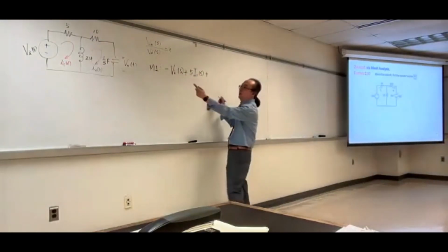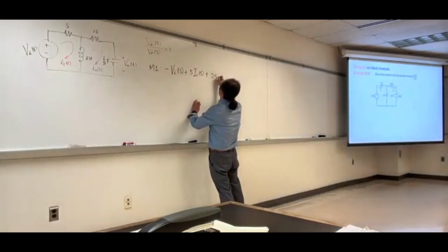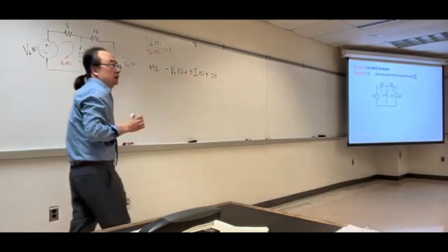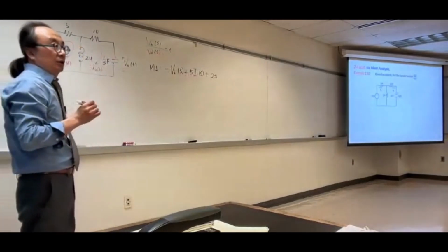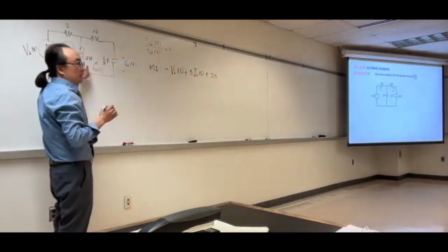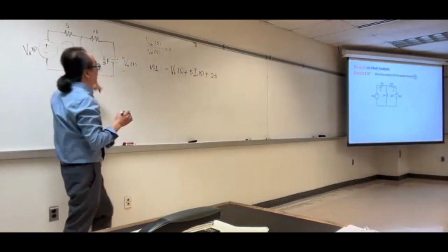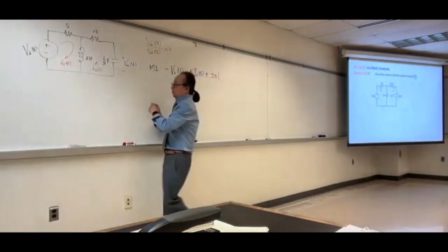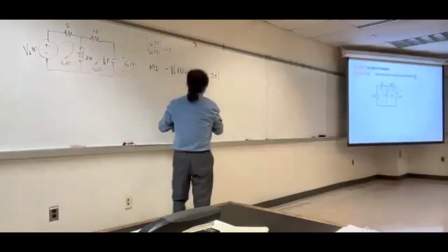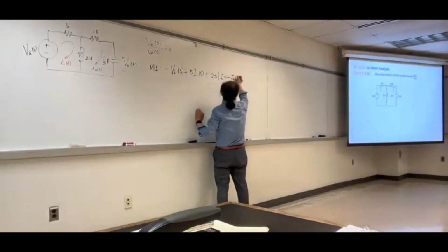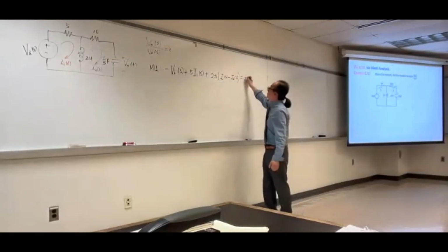LS, L is 2, S. So that's the Z, and then we need to multiply this times the current. But these are mesh currents, they are not going through this element alone. So we need to write, this is the reference to I1, so I1(s) minus I2(s) equals 0.